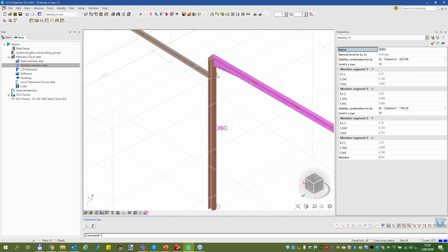But as soon as you have a hinge here or something else, it can give you obscure, weird results. You would expect, for example, 1 here and it gives you a value of 4 or 5, which influences your steel code check, because your buckling check will most probably fail in that case. So this is a way to circumvent that. A better way, which is the next thing I will explain, is just do a second order analysis, and you can forget about buckling because it's already taken into account during the analysis. So no need for the flexural buckling check.